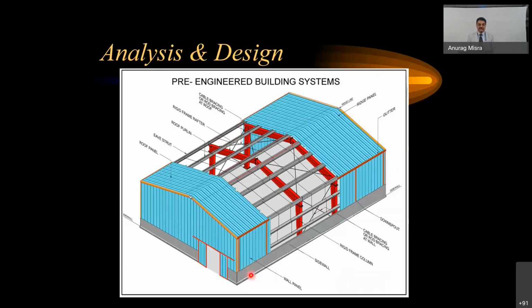So if you have some distance, some wall here near the bottom, and then you are going to have the sheet cladding here, then for these supports you have to design them, and then these are the stays, normally in the form of thin rods, which would actually keep the members in alignment and would help the stiffening of the wall panels. Right?